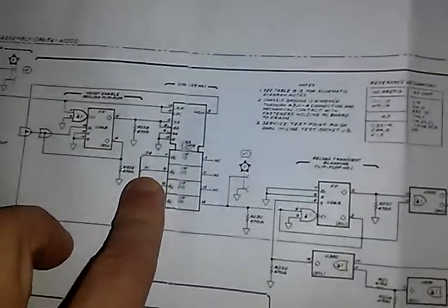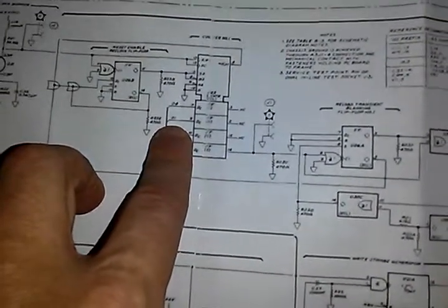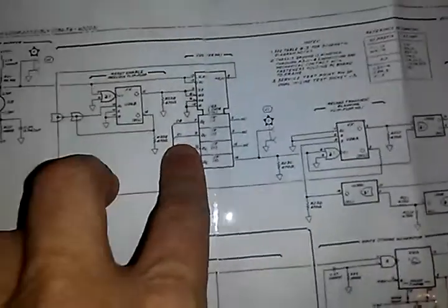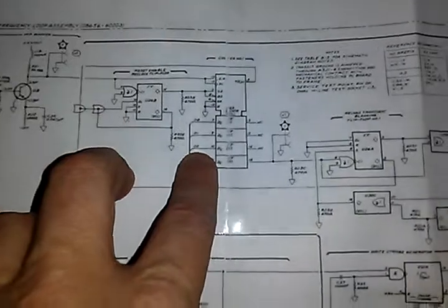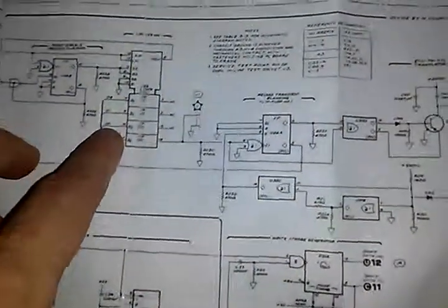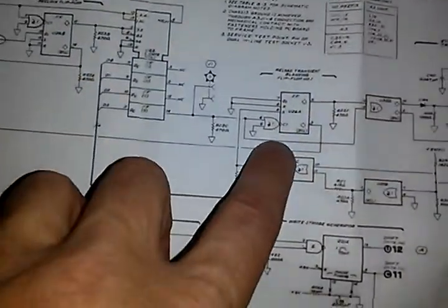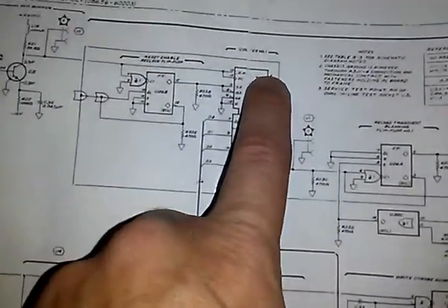Now, that's the way it's supposed to work according to the data sheet. But the way this circuit is designed is that it doesn't do that except one time, and that is on the initial count. And what happens is that after the initial count, this latch is reset, and this is held high.